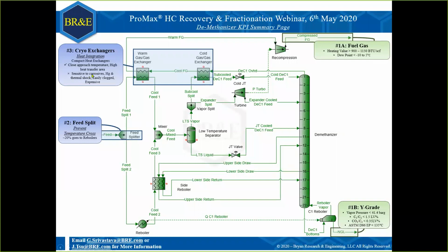However, you also have to be very mindful of corrosives and mercury because it's made of aluminum typically. And because of its very sensitive nature, you normally take a very long time to start it up because you don't want to thermally shock it. And of course, the small channels make it easily clogged and it is generally more expensive than your bread and butter shell and tube heat exchanger.